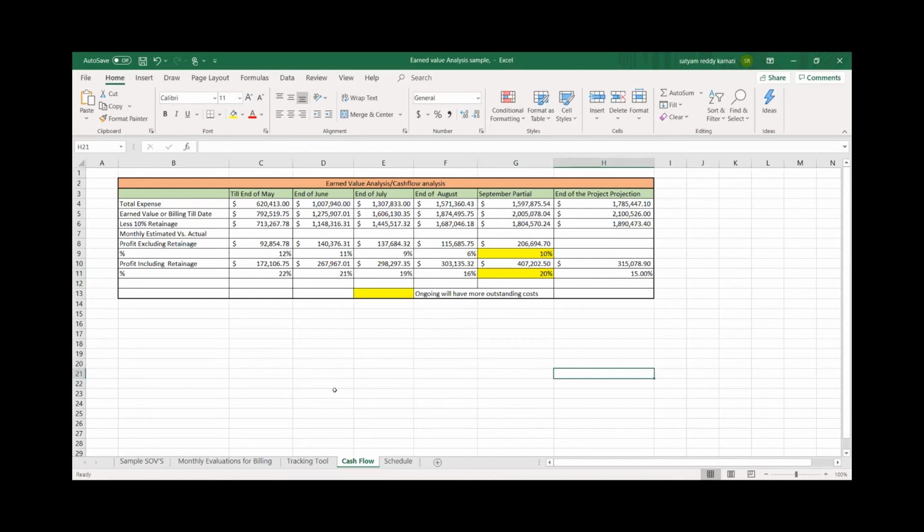Yeah, just the same example. 200,000 for 300 linear feet. I have, let's say, $1,500 for every linear foot. And if I have finished 100 linear feet, I have finished $15,000 worth of work. That's how we track. So it's true earned value and true planned value. And you compared that with the actual cost. Yes. And he's asking, yeah, monthly progress.